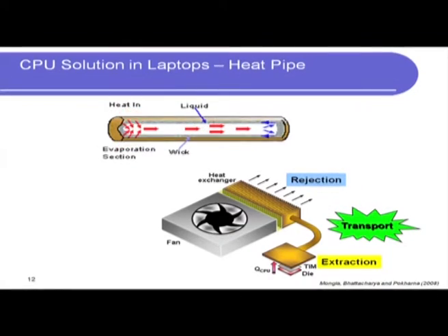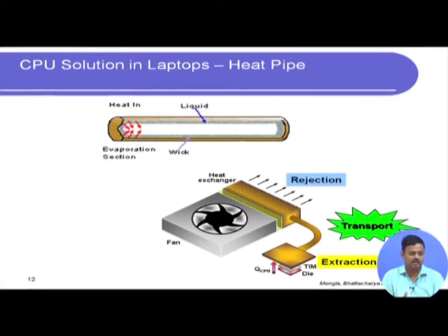I used to work for Intel for many years, and I was a thermal designer for laptop computers, so I worked with this for almost 5 years, and in my 5 years of experience, I never saw a heat pipe that failed. There were other reasons for which the laptop failed, but not heat pipes. The fan would fail. There may be dust accumulation at the heat sink or between the fins, etc., but heat pipes never. It is so reliable, and today it is extremely cheap also. A typical laptop heat pipe costs less than $1, in fact like 30 cents or so.